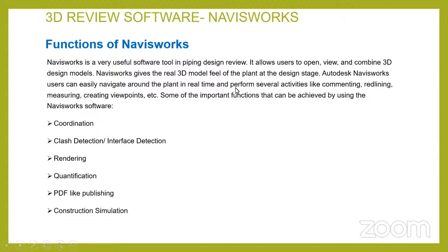From the initial stage itself, the consultant will prepare the drawing in Plant 3D, then they will import it to Navisworks, and the client also can see it in Navisworks. So what are all the advantages? It gives coordination, it gives clash detection. Clash detection means interference, like whether this pipe is interfering with the other pipe or not, whether the instrument point is clashing with the nearby pipelines or not. All that we can see from Navisworks, because it is showing the 3D model.